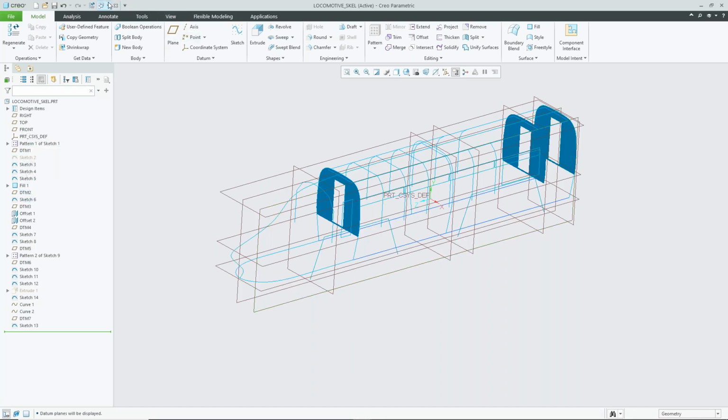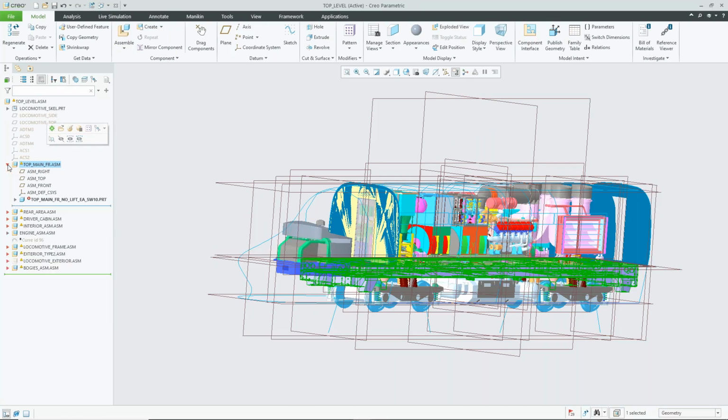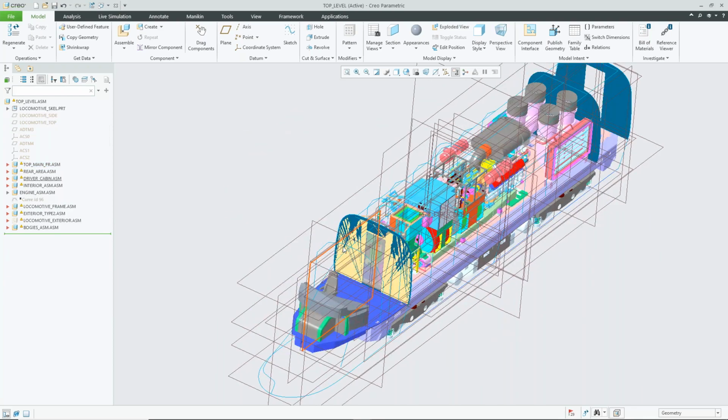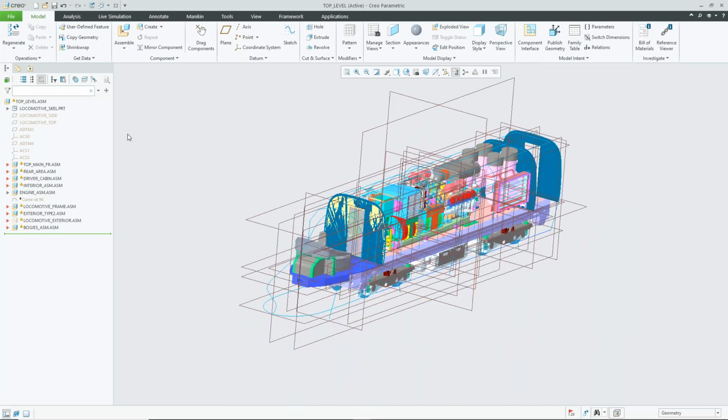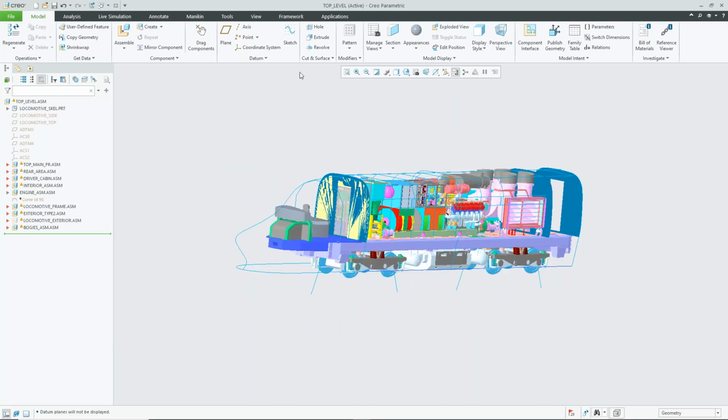So for that, when we start looking at some of these other items, no, this one isn't there. I'll show it in the other one. But what we will see is inside of these other components or assemblies, we've copied that skeleton or references from that skeleton. Because this was simplified, we did not copy anything in there because we just simply used the shrink wrap components. We just wanted to make sure everything was fit properly.